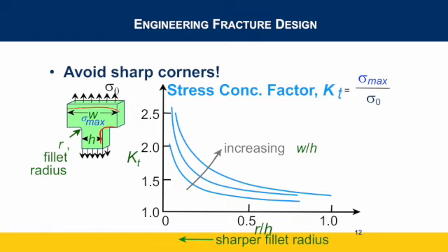Obviously the upper part has a much bigger cross-sectional area, so for the force being applied, the stress is much lower. Stress is going to be a lot higher here. Same force, much smaller area. Where is this material going to want to fail? Typically it's going to want to fail on the smaller area, but it's also going to want to concentrate in the transition between the two materials, right? And if the material has a right angle, or a 90-degree angle, versus a smooth curved angle, it's going to have a much different result in how it fails.